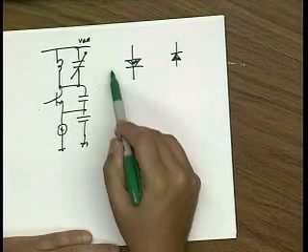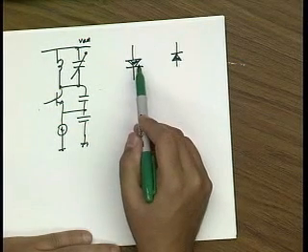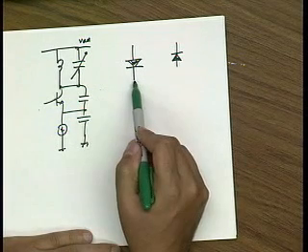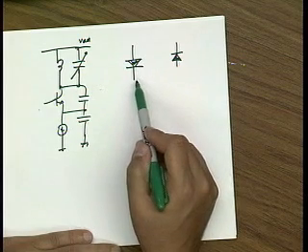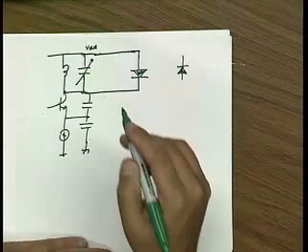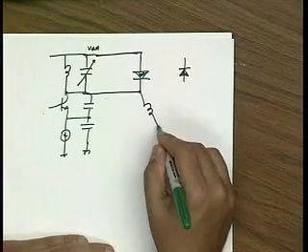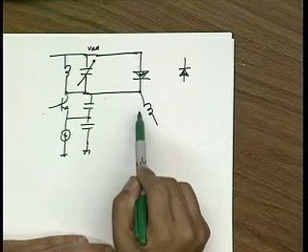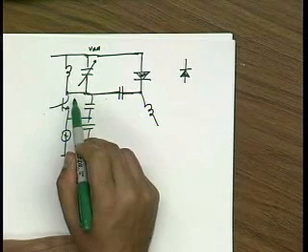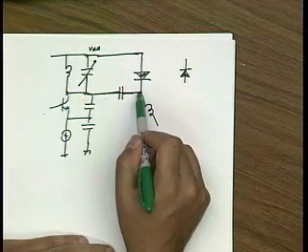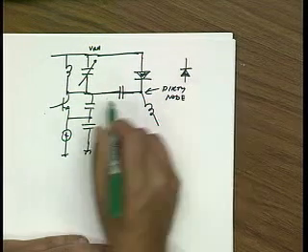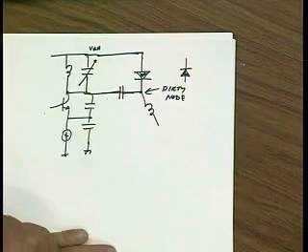And so if I use this configuration, first of all, it would put the dirty node onto my tank. And second of all, I would need a voltage larger than VDD to reverse bias it, right? So if I use this configuration, in order to reverse bias this, I'd have to use a voltage larger than VDD. That means I'd have to put a cap here to avoid connecting that here. And this dirty node is connected to my tank, right?